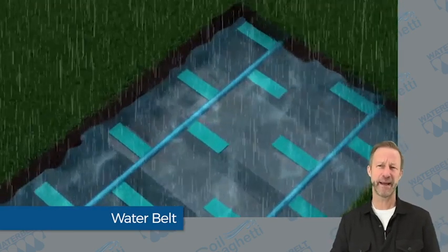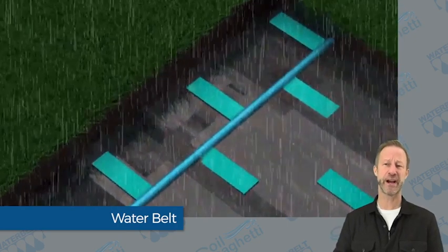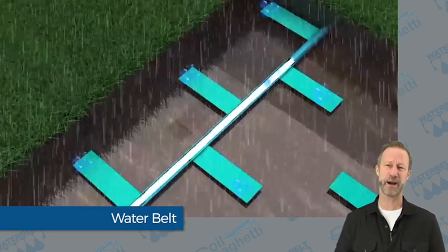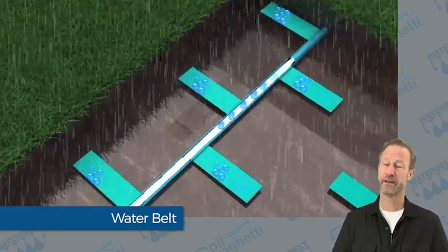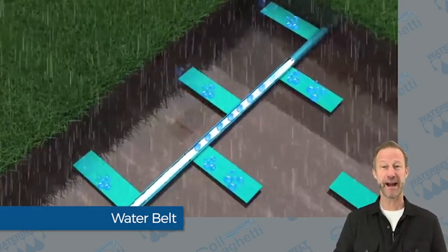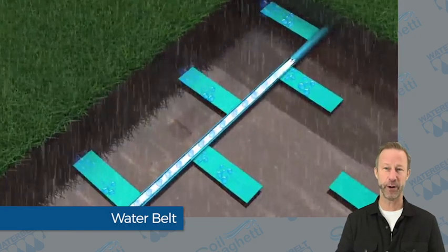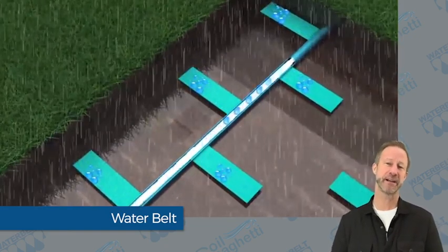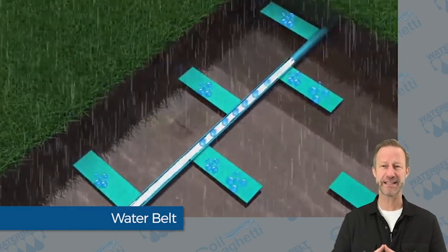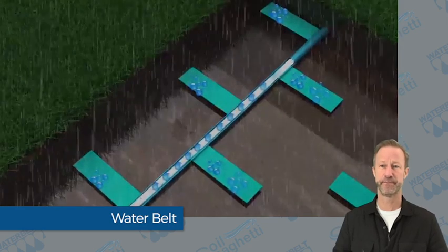Waterbelt's a very efficient mechanism for water collection, but it's impractical to claim that it will transport water as efficiently as pipe. The capacity of the microchannels is simply too small. The solution is combining components based on their strengths. In other words, the combination of Waterbelt, a perfect mechanism of water collection, plus pipe, a perfect mechanism for water transport, eliminates hundreds of years of failed drainage problems caused by blocked pipes.